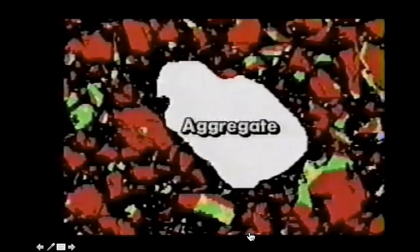So this is the model from NIST. Particles of cement are arranged on a computer display. The computer determines regions of the particles that can dissolve into water. The bits of dissolved cement diffuse through the water in a random manner and react to form solid phases according to certain rules. After a cycle of dissolution, diffusion, and precipitation is complete, the computer proceeds with another cycle.